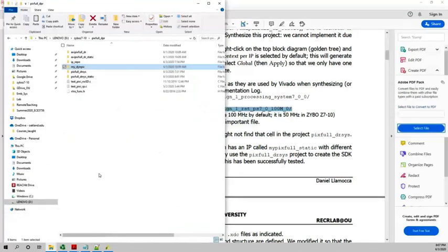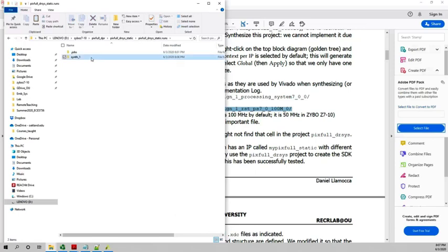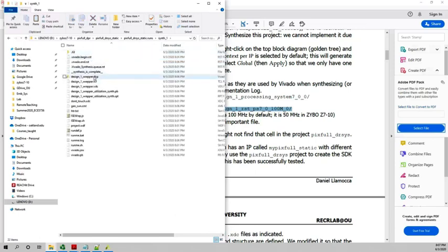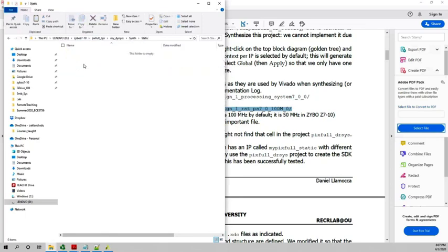So you're gonna go here. You go into, remember, the static one, and you go to runs, synthesis 1, and then you go here. That is the static file description. So the netlist, you wanna copy, and you are going to place it onto synthesis, of course, static. There you go. That's the first step that you need to take.